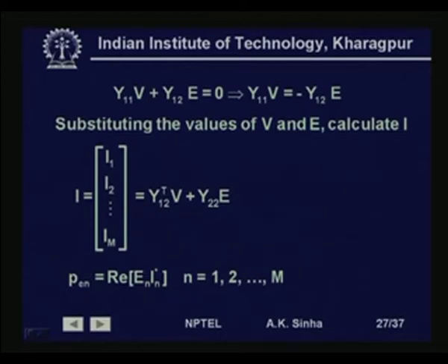So, Pm minus Pe will give us the accelerating power, and using this accelerating power and the swing equation, we can solve the swing equation and find out the values of delta and omega at the next time step, and so on.